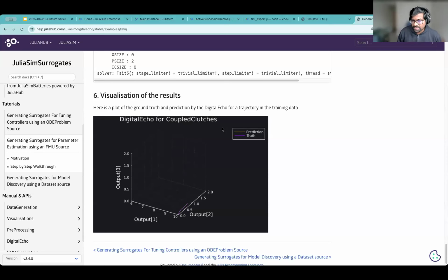Now, JuliaC will become the standard way in how we compile and ship these FMUs. Specifically, JuliaC does a few smart things to get rid of most of the Julia runtime so that it can give you as small a library as possible. So that's going to be the new way we're going to export FMUs. That of course is a work in progress. Again, it's on the latest Julia that's not quite released yet. So we are expecting to incorporate that and get those FMUs down to 2 or 3 MB. Anyway, that's a long-winded answer to say that today it's 100 MB, tomorrow it's going to be 2 or 3 MB.